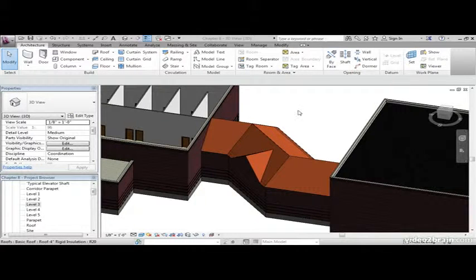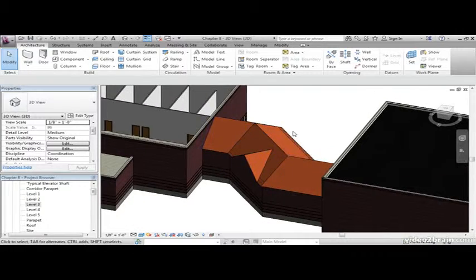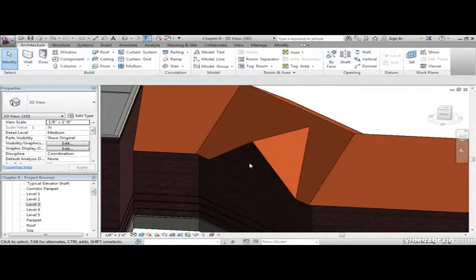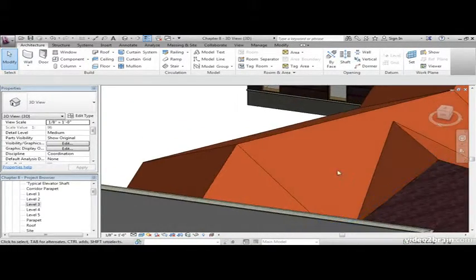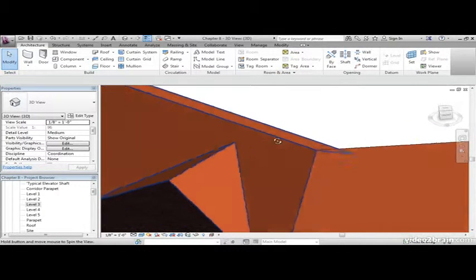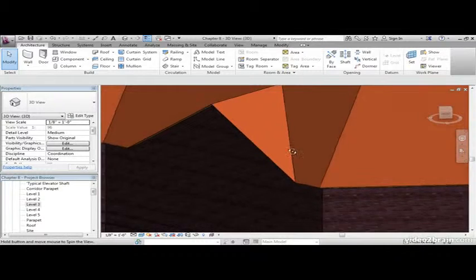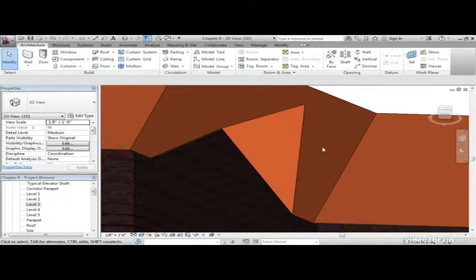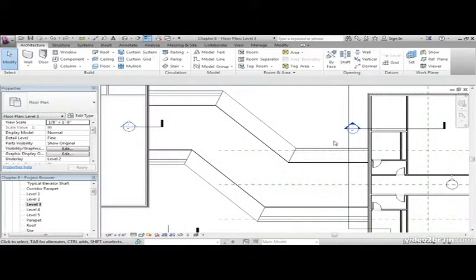As you can see, we have a dormer in here. Take a look at my example here. Here's a dormer we're going to put in. It's pretty nice, right? It's the same 9/12 pitch. Doesn't quite make it to the ridge, which is kind of the way we want it. We want it lower than the ridge. It's laid out symmetrically and against the front fascia.